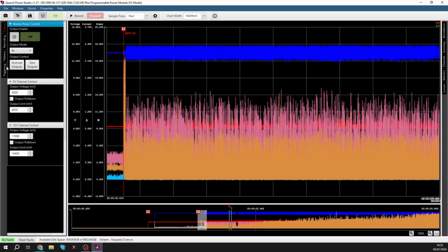We can set the output voltages, so we can tune the exact voltage with this device for the drive, so we can overvolt and undervolt. All these controls are on here as well. We control both channels individually, and we also have additional protection for the drive you can set separately to avoid going into an accidental overvoltage and damaging it.